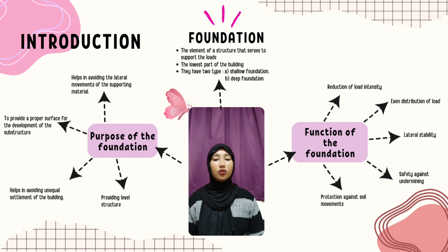and flood water. Lastly, protection against soil movement: special foundation measures prevent or minimize the distress or cracks in the superstructure due to expansion or contraction of the subsoil because of moisture movement in some problematic soils.